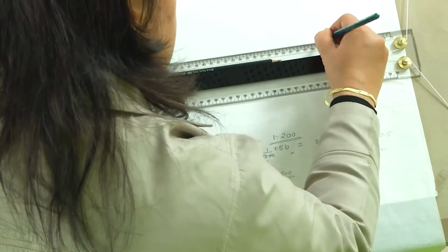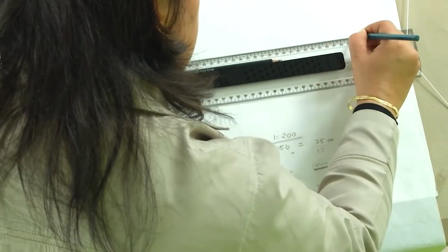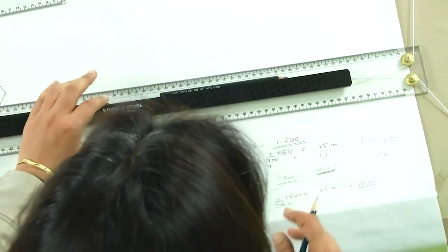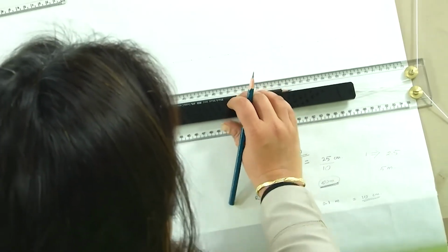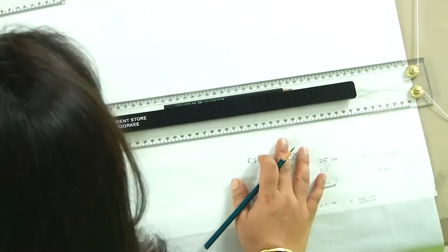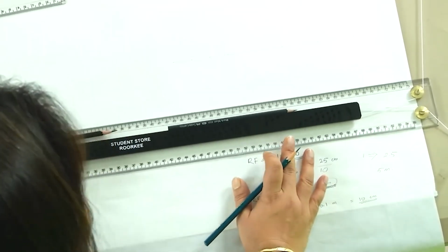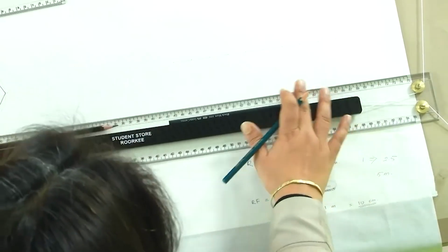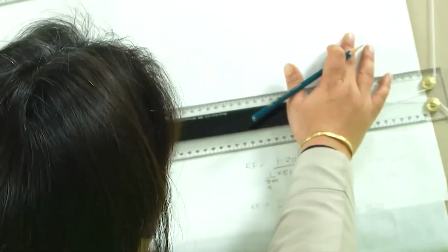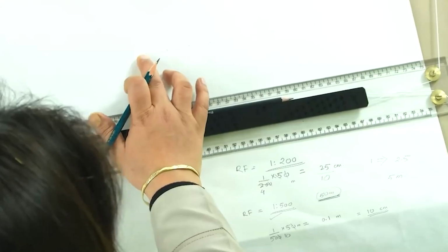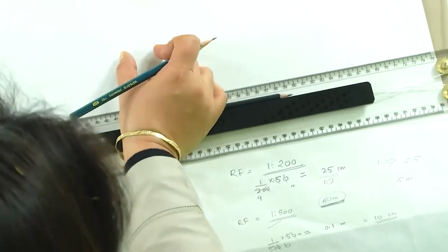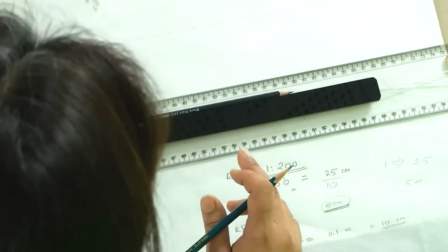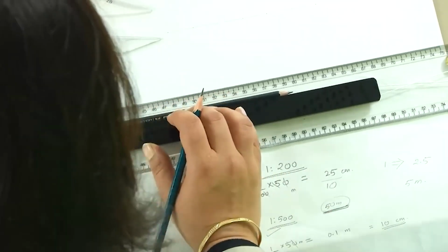So, we make these equal divisions of 2.5 centimeters each. We could have drawn it using the division of line method, but since it is a simple unit and we could divide using the scale, that is what I have done. And now we have to divide this first division into 10 equal parts, and we will do it using the same method as before.